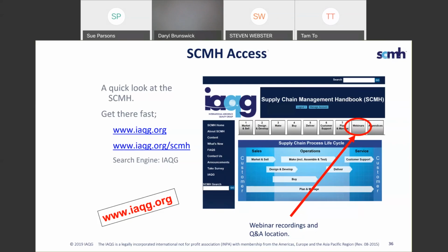So you should be continuously revisiting these forms, reevaluating and reprioritizing, and taking actions against areas where you have high RPN numbers. As you learn more and more about the process, you should be continually working that. It shouldn't be something that you do once and you're done.